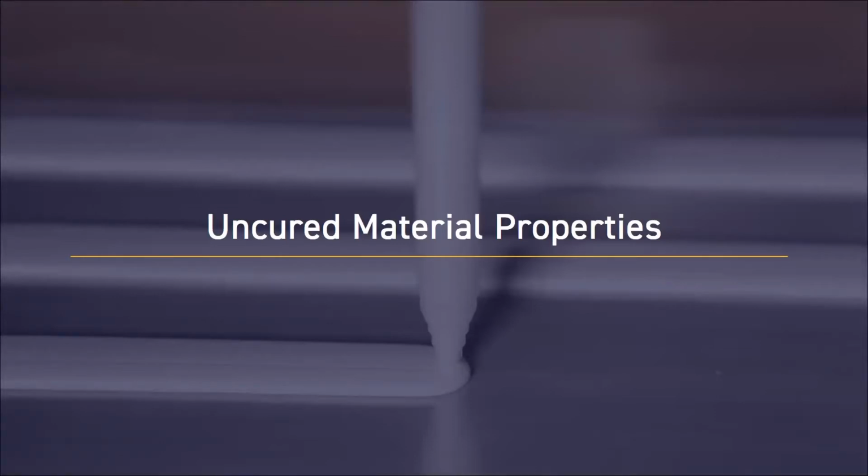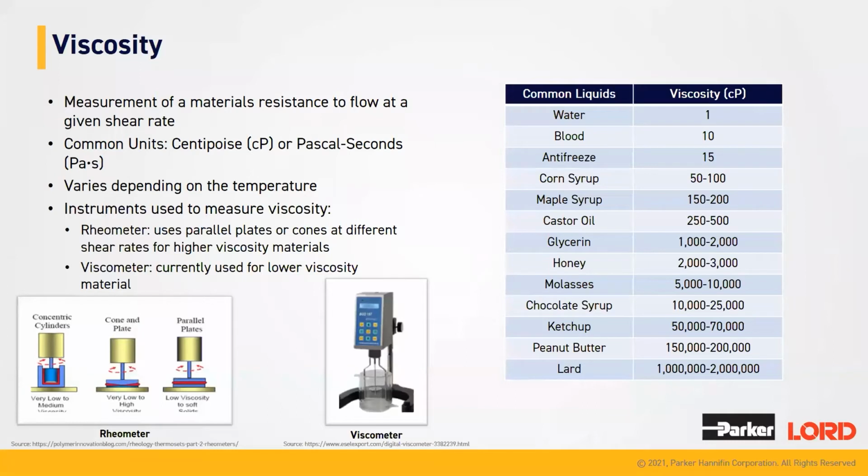The first topic we're going to be covering is uncured material properties. The first thing is going to be viscosity. Viscosity is one of those properties that we interact with on a day-to-day basis, even though we don't necessarily realize it. Viscosity is the measurement of a material's resistance to flow at a given shear rate. Common units for viscosity are centipoise or Pascal seconds. The viscosity of a material does vary with temperature. When it comes to evaluating viscosity, a rheometer or a viscometer is used. You can see that at the bottom of the screen there.